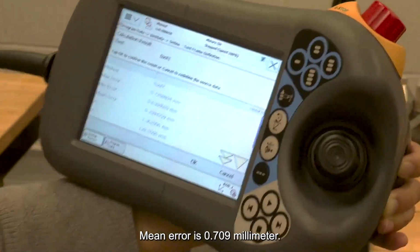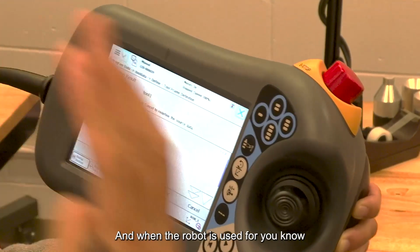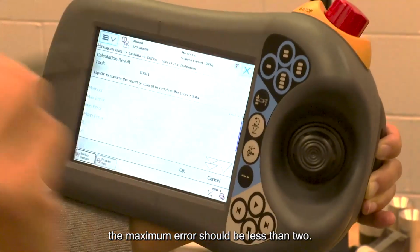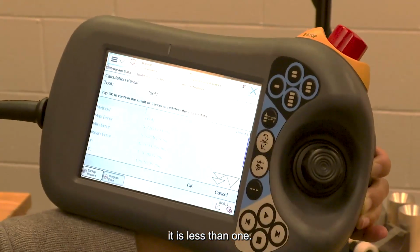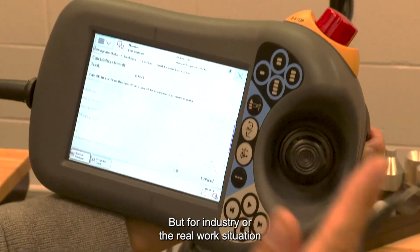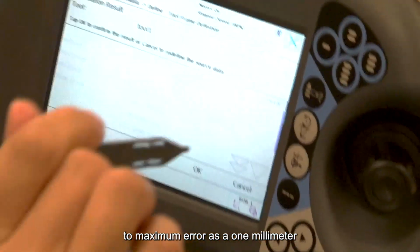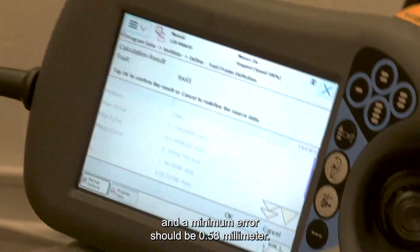When the robot is used for education or demonstration purposes, the maximum error should be less than 2, and the minimum error less than 1. But for industry or real work situations, the error should be brought down to a maximum error of 1 millimeter, and a minimum error of 0.58 millimeter.